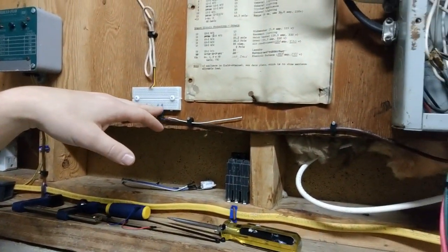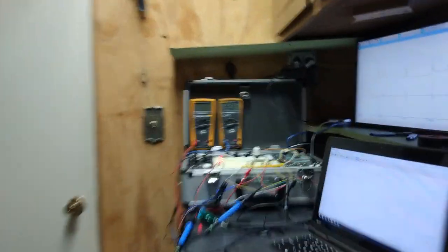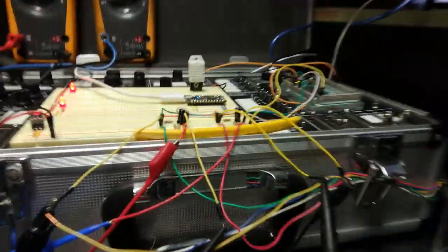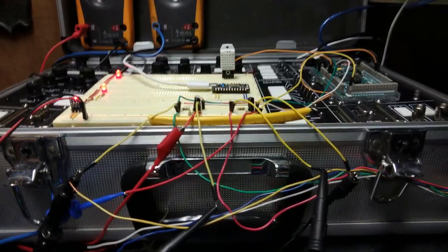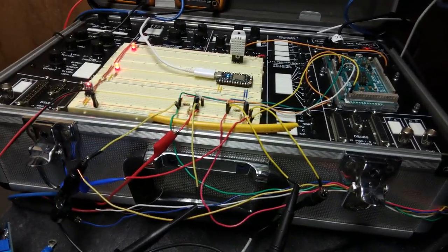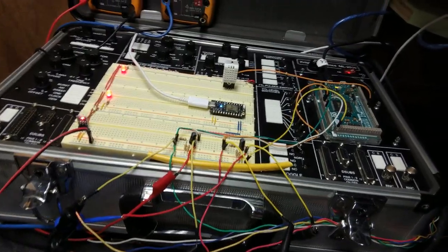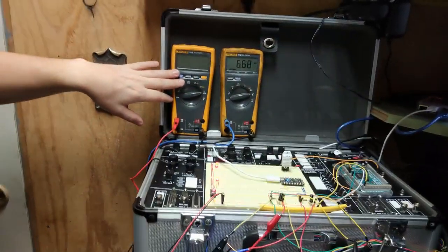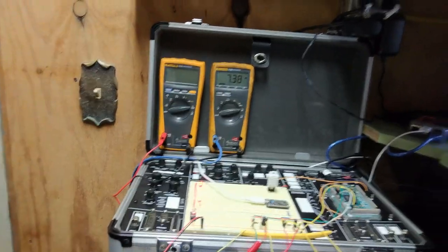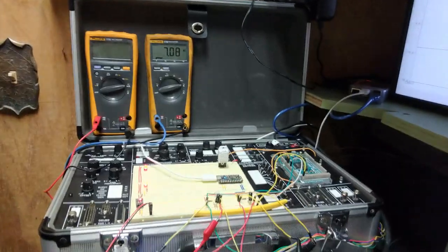We've got this set up so that we can safely work on the CT circuits on the back end over here, where we're running a voltage divider on it so that we can increase the voltage and have it in a positive voltage domain so that we can record it on the Photon. The Photon won't go negative. But before it goes in there, it comes through these two meters, which display instantaneously what's going on and how much power we're using.